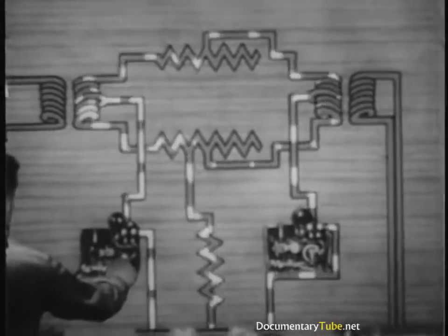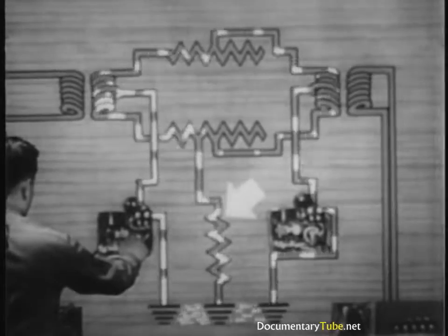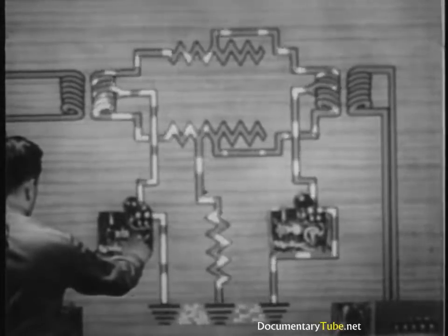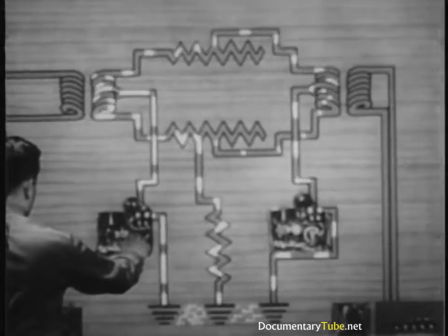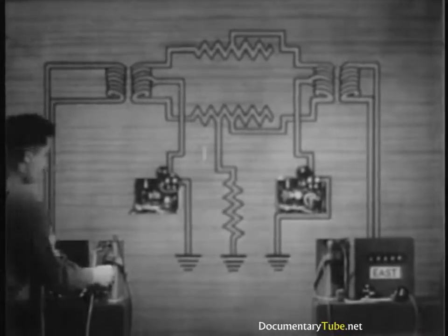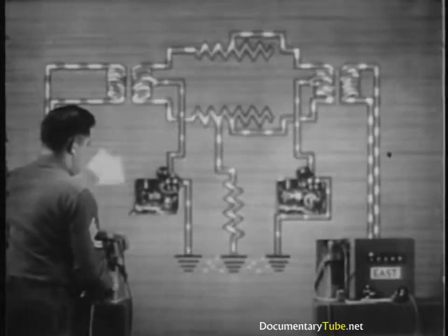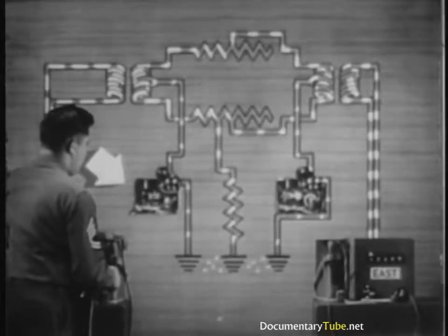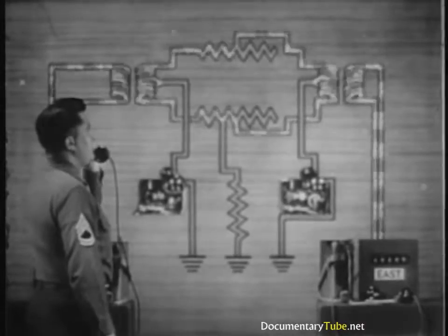When one wire is grounded, both channels are generally still usable. Telegraph current is weakened, though, and interferes with the telephone. Ringing current is also weakened and may interfere with the telegraph. Voice current is unaffected.